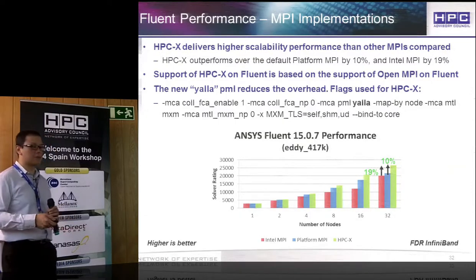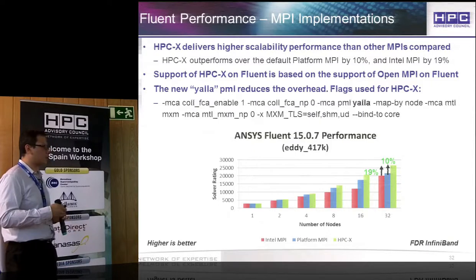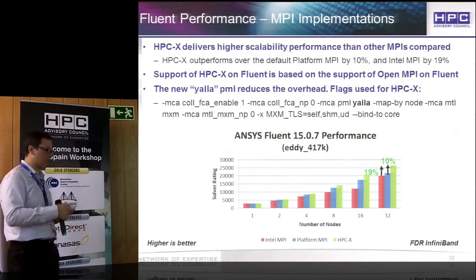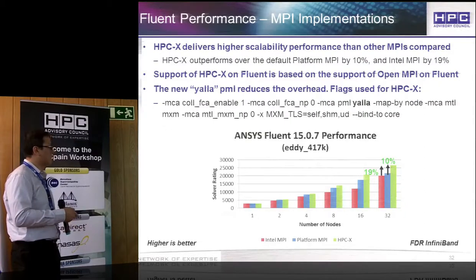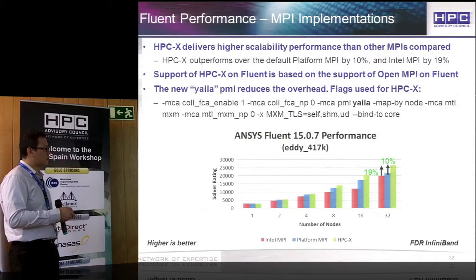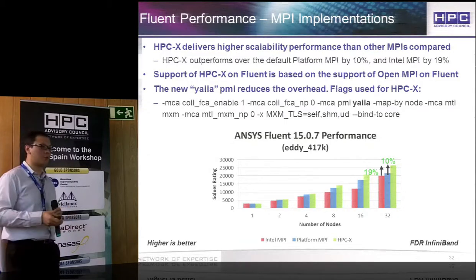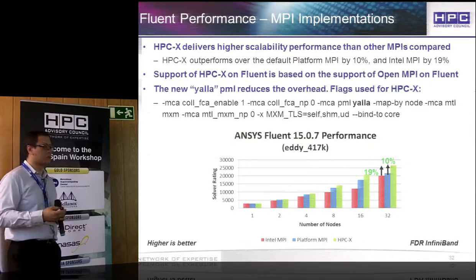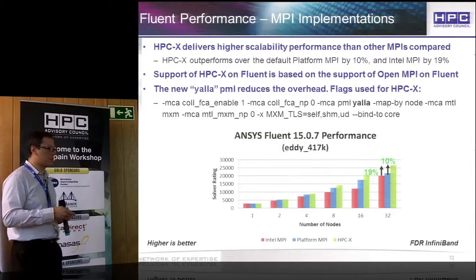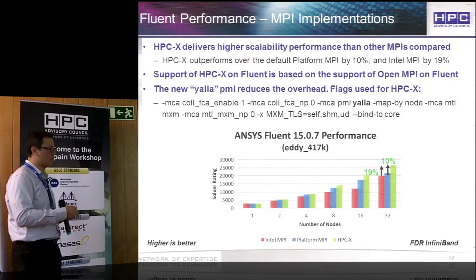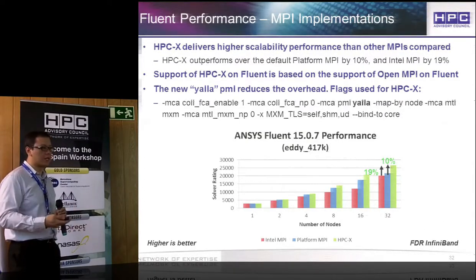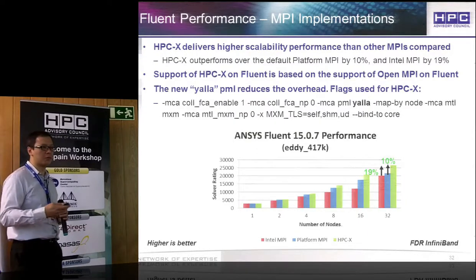So later on in some of the slides, I'm going to show you in the profile what kind of communication pattern there is and why this would actually benefit the performance. Inside these flags here, this is for enabling something called MXM, which is yet another module that comes with the HPCX package to enable the scalability of the performance. And eventually, I'm going to show you a slide that compares the best performance listed on the ANSYS Fluent webpage with my performance game here, just to see how far or how close we're getting to the best numbers.